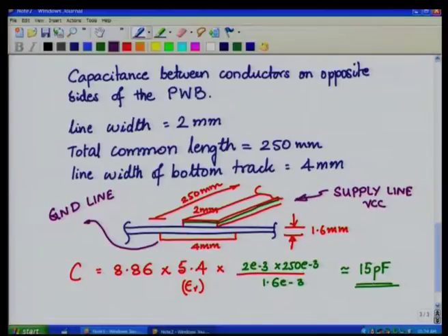These can be used as decoupling capacitors when it is a distributed decoupling capacitor, as these two lines are connected to various digital circuit loads, like we saw in the last class, the output stages of the gates being totem pole or composed of top and bottom switches, where during switching transitions you will have huge current spikes.